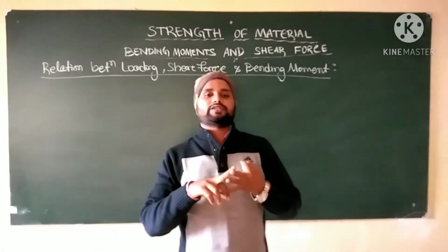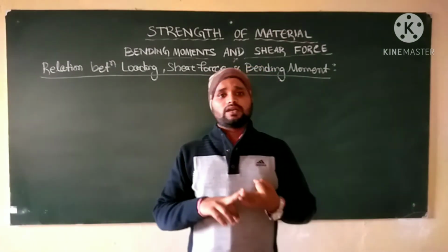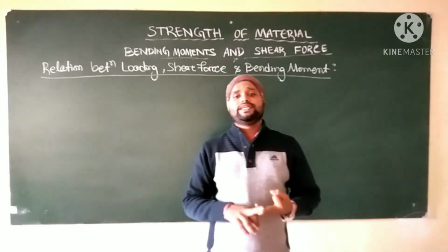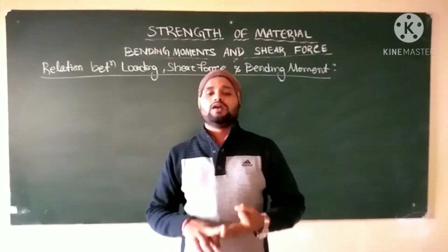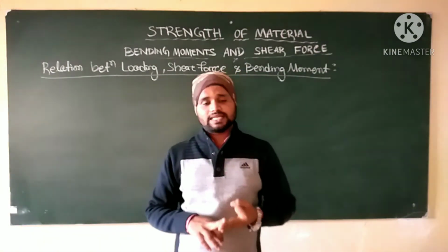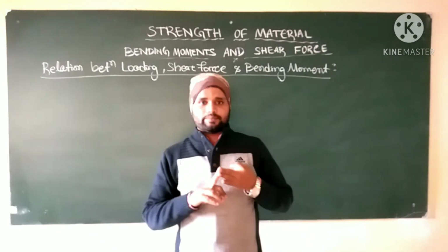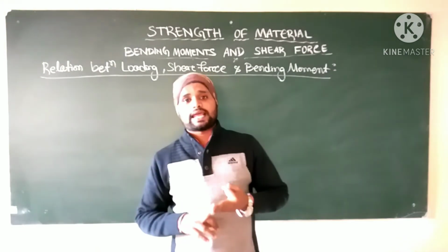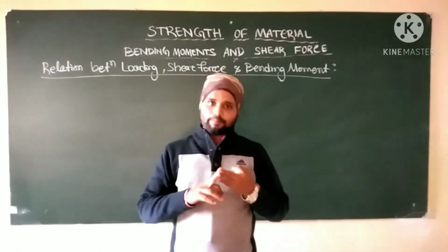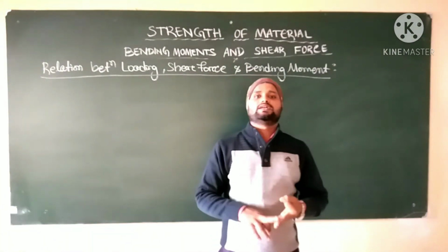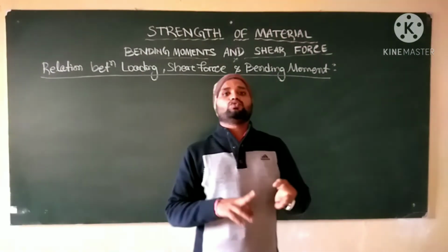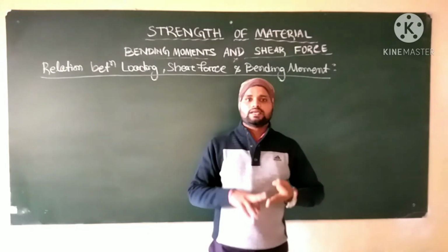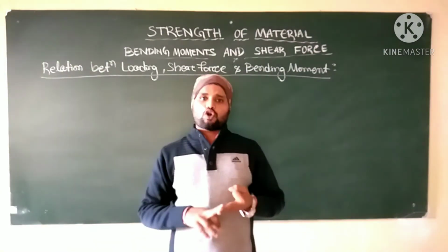Next, third point. If there is a uniformly distributed load between 2 points, then the shear force changes linearly. That means the shear force line will be an inclined straight line. But the bending moment changes according to parabolic law. That is, the bending moment line is a parabolic curve.